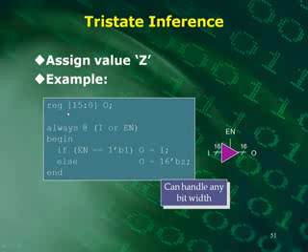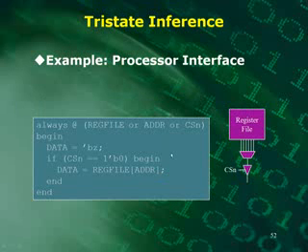So you could do it this way instead. Say we have a 16-bit bus we want to tri-state under certain conditions, and you could just write the code like this. So if enable is high, then the output is equal to the input. Otherwise, if enable is low, the output gets turned into tri-state. And this way you can handle any bit width.